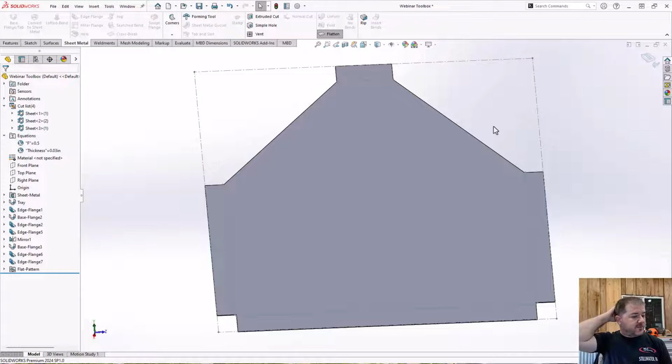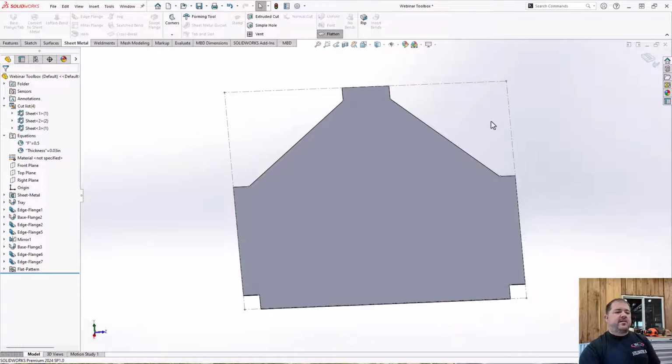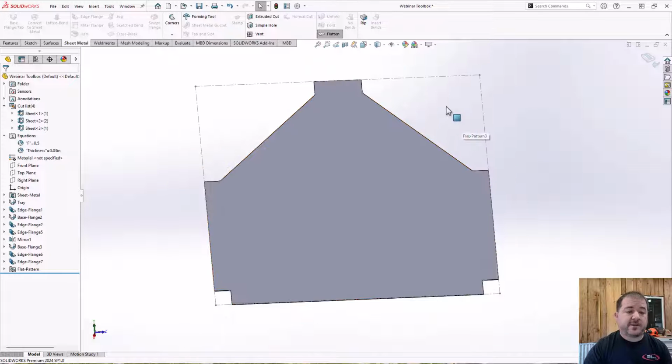But when you start to deal with situations where you have lots of bends compounding on each other, maybe you have some overbends or underbends, different angles of bends, different thicknesses of material, those bend allowances only apply to one combination of material thickness, bend radius, and bend angle. So it's a lot of manual work to do anything other than 90 degrees on standard materials.